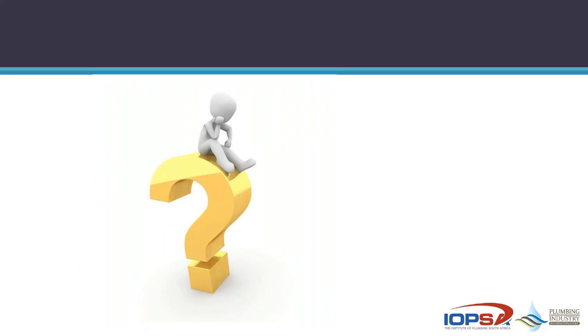Yes, indeed. One of the slides that we touched on two weeks ago was that every installation shall have one open vent. So the vent valves are considered auxiliary, or you could say they're dealt with under open vent, but the standard clearly says that you shall have an open vent on every system.